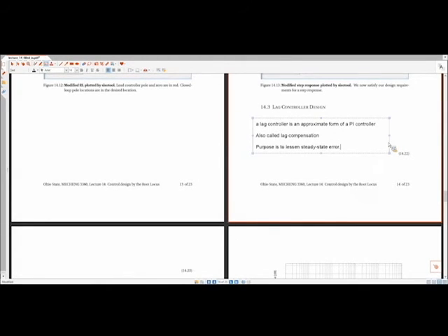So just as a reminder, making a comparison to something we've learned already before, if we had a proportional integral controller, we had the form of G1 of S is equal to Kp plus Ki 1 over S. All right. If I want to write this under a single denominator, I can write this in terms of a single gain out front over S, 1 plus Ts.